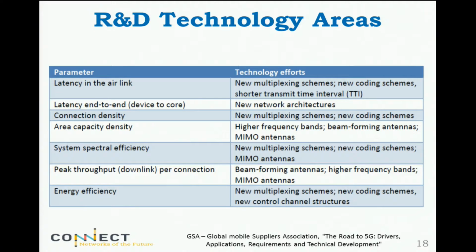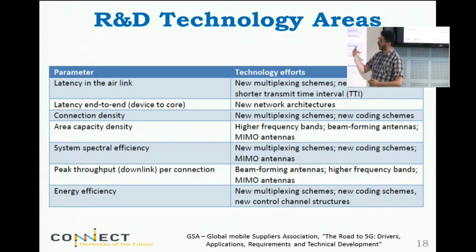What they try to do, and they are actually accomplishing more or less with full duplexing, is to have the same time-frequency tile, the same resource, used for both downlink and uplink. The main problem with this technology is what is called self-interference. When you transmit, part of it is going to impact your receiver, because the receiver is also active, at the same time and the same frequency. So this is coming back to you, in a sense. And they are developing self-interference cancellation schemes, so they're working on that. We are still far from the promise of twice the spectral efficiency they are claiming, but there is work going on.